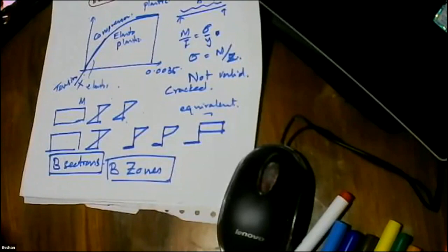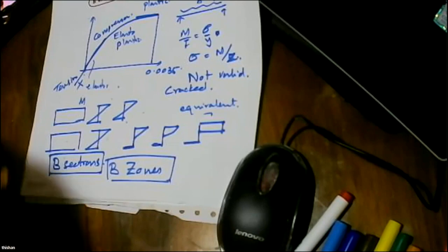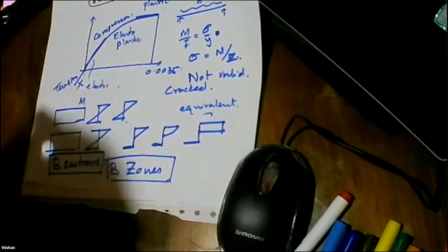Right. Then we teach timber design. Why? Timber is a natural material. So when you learn how to do a timber design, we are learning how to use a natural material as a structural component and how to design it. Then we teach masonry design. Why? In masonry design, the equation is stress equals force divided by area, not the bending formula. What is applicable is stress equals force divided by area.